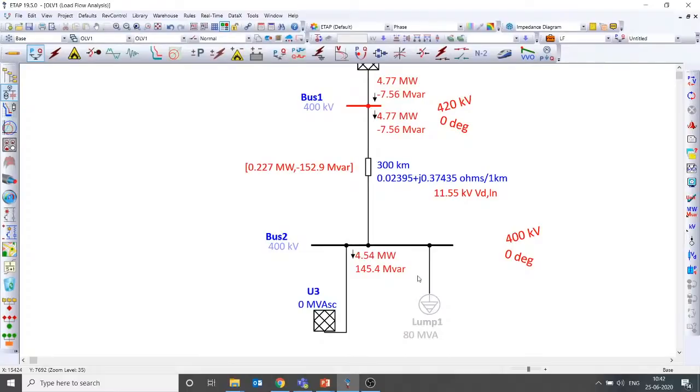There's a question from Satyanarayan Ramachandran: how do you set the criteria for modifying PV to PQ on violation of the reactive power limits? You need to go to our generator model. In the generator you might be giving Qmin and Qmax, the reactive power limits, based on the capability curve of the generator. So when your reactive power limit hits, automatically your PV bus will be converted into a PQ bus. That's to answer Satya.